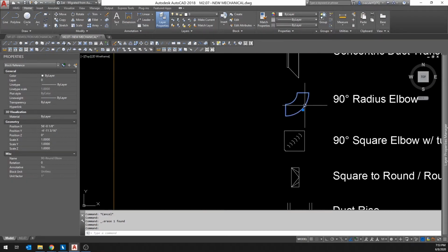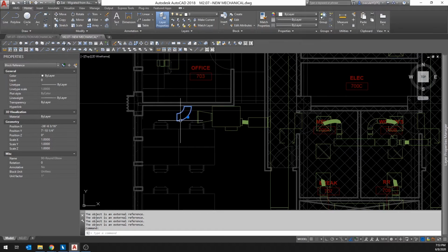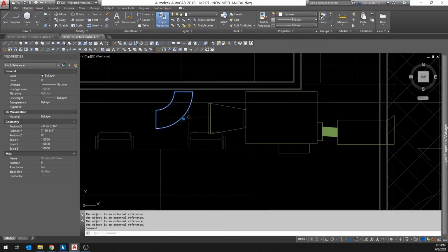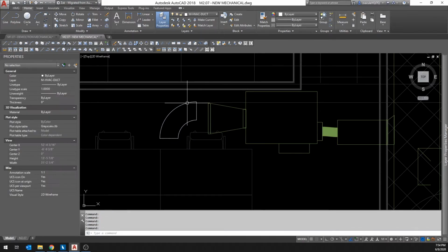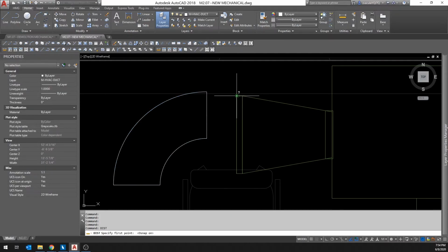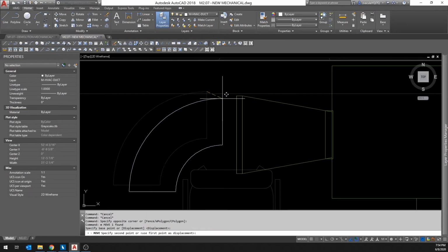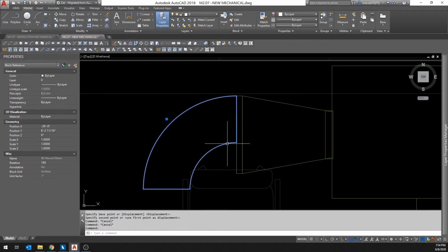The scaling tool will let you match sizes a lot easier without having to do any calculations or just kind of guesswork. All right, so I'm going to rotate this 180. So we know that we need an elbow essentially to be, this line needs to be 20 inches tall. So if I run dist, which is just a measurement, see that's 1'8", so that's 20 inches.